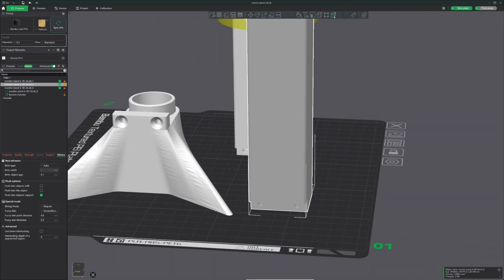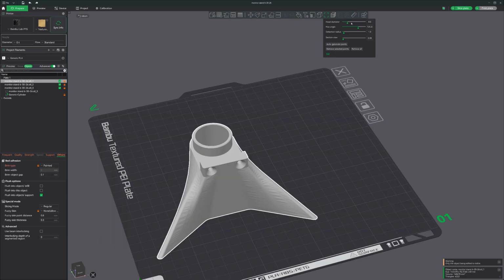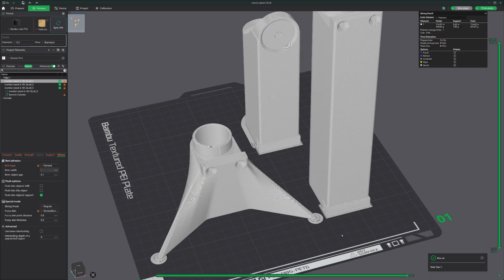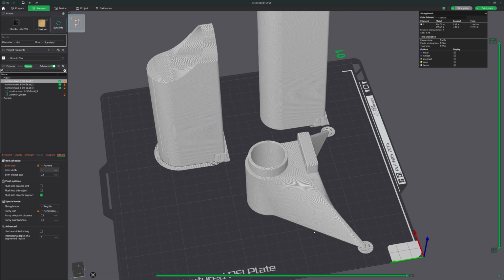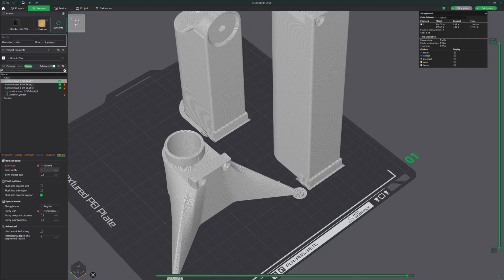Okay, there's a couple more paint tools here to talk about. Here is brim ears. This is what I was talking about before, how you have different types of brims, and if you paint it, then we're going to do the ears here. Let's increase the diameter and put some right there and see what this does. There we go. This little brim will hold down these lines right here for these walls pretty well, especially in PLA. This is more than enough to hold this part down. I recommend using these on hard corners or edges that are likely to pick up and curl.